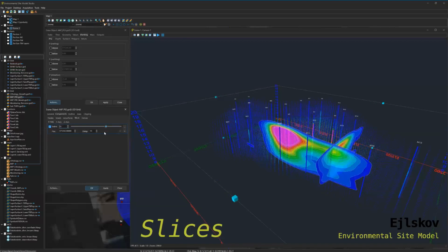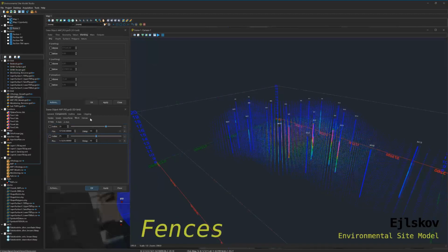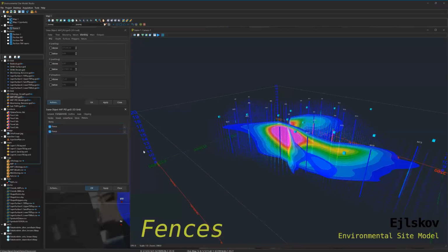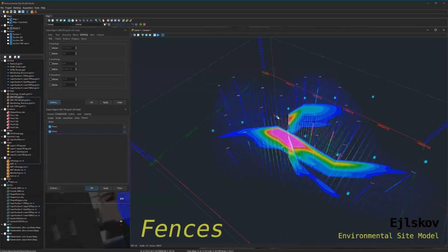So rather than having a remediation done, let's say, more homogeneously across the whole site, where you think, I have to assume that that area is as contaminated as another area, with the extra data available, I may find that there are 100 square meters of that property that really have a lot of contamination, where I need to use more budget, and then I may find that another 100 square meters are actually not impacted at all, so I can avoid doing any remediation in that area.